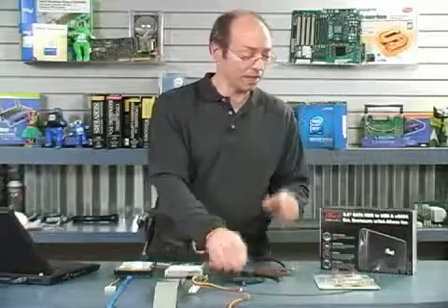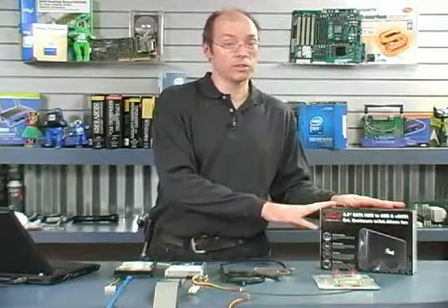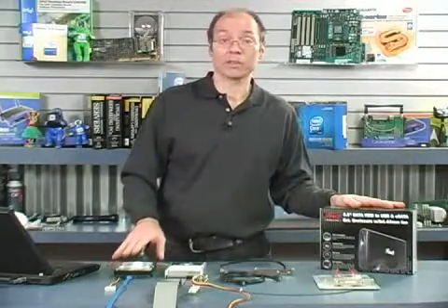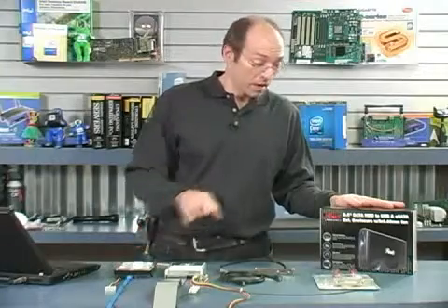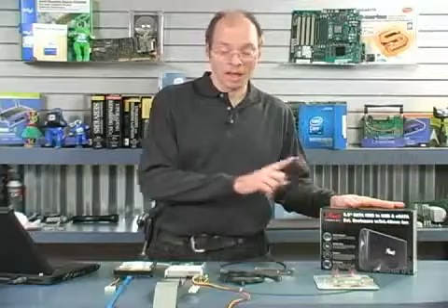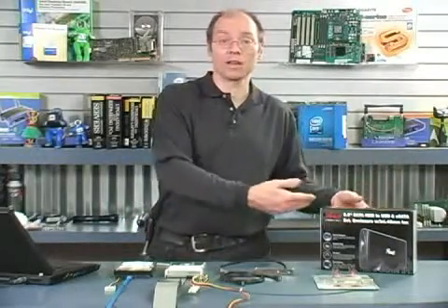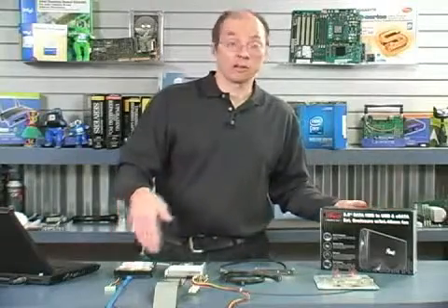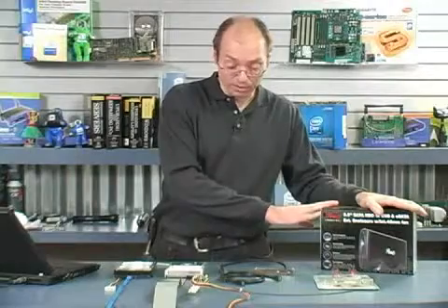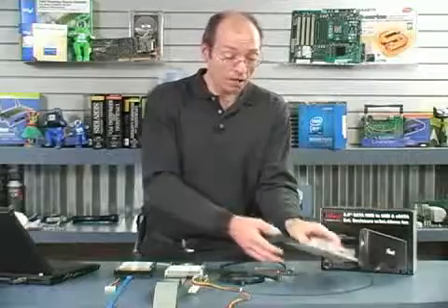Now, here's one disappointing thing. Virtually all of the external enclosures that support eSATA only do so at the 1.5 gigabit per second rate. So even if you have a 3 gigabit per second drive like this one, it's only going to work at 1.5 gigabits per second via eSATA. Now here's where knowing about that jumper may come in handy, because if you build it and it doesn't work, you may have to install the limiting jumper depending upon what type of circuit board is in the particular enclosure that you're using.